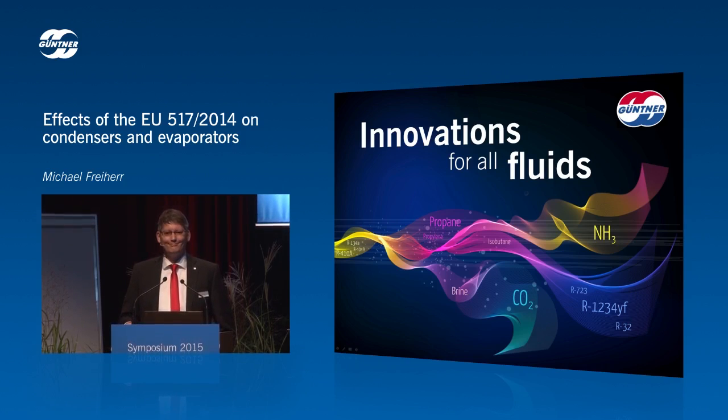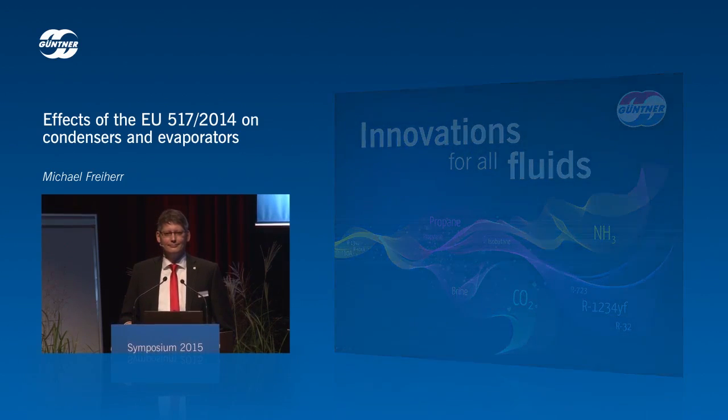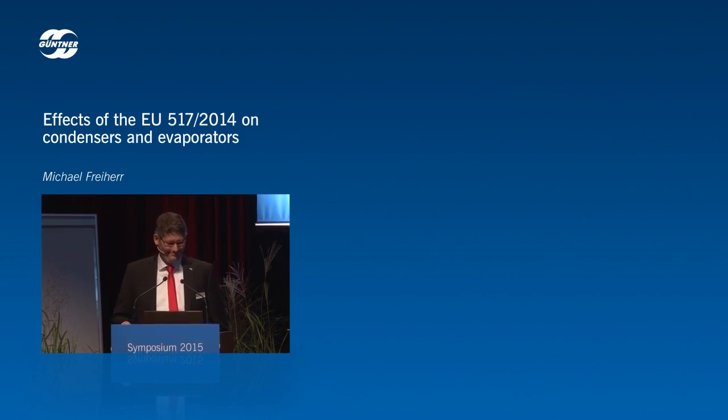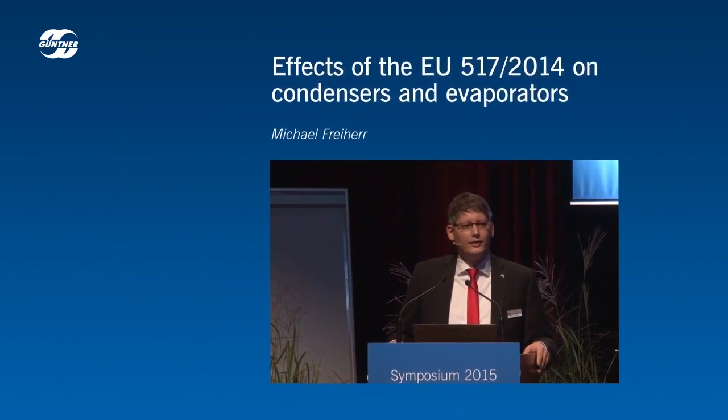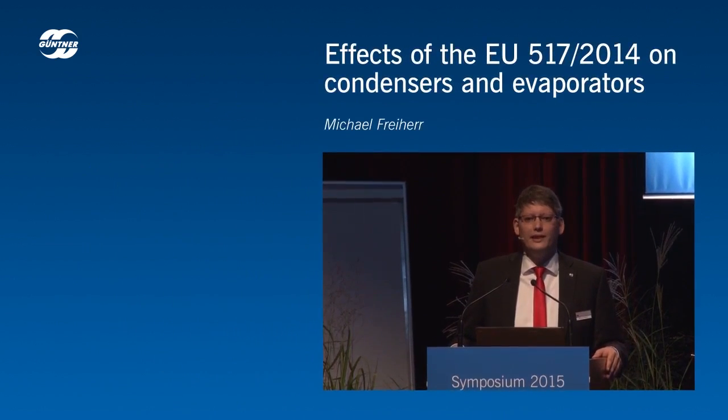I have a question. Zeotropic blends are sold as drop-in solutions for 404A plants. If you were an operator of a 404A plant, would you restructure your system? You can do that. This is something I did not touch upon in my presentation. This was the design for new plants. The drop-in case should be looked at separately.